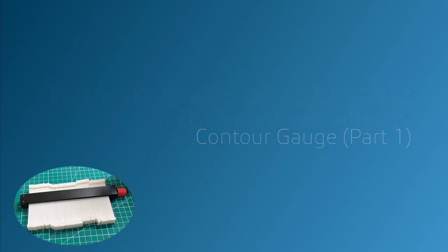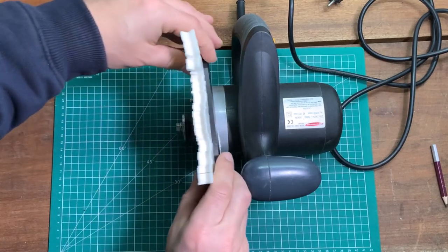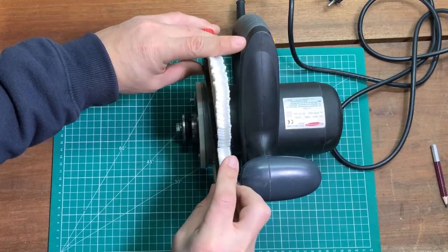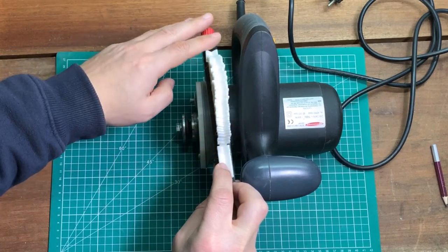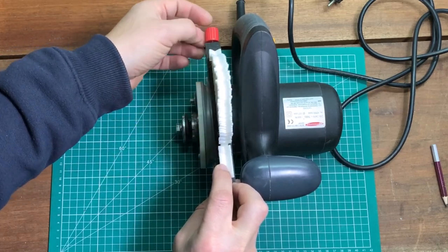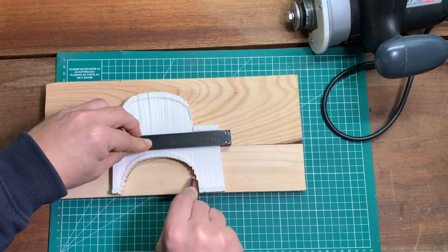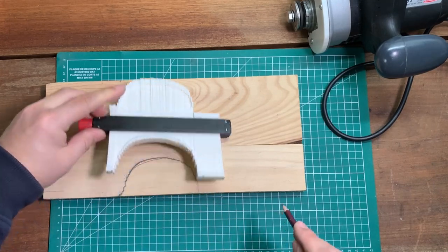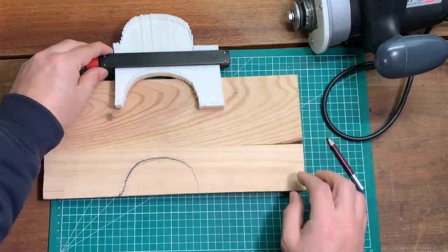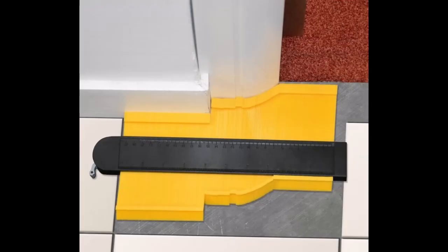Well, here I would like to clamp this circular saw to make a table saw, but I tried to measure the saw contour and the result was poor. So I use a contour gauge to take the exact contour and reproduce it on a piece of wood. I block sliders and positions to keep the right contour when I draw on the wood board. Then I cut along the line to clamp the saw safely. It also works to cut tiles in complex corners like around this door frame.